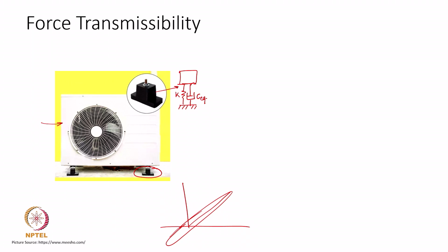It's actually there is no viscous damping here, it is all structural damping, but for the sake of using it in the equations that we have already derived, it is quite common to numerically find this equivalent damping coefficient by measuring the area within this curve, which denotes the energy dissipated, and that we have had enough detailed discussion of how the equivalent viscous damping coefficient value is obtained. Okay.